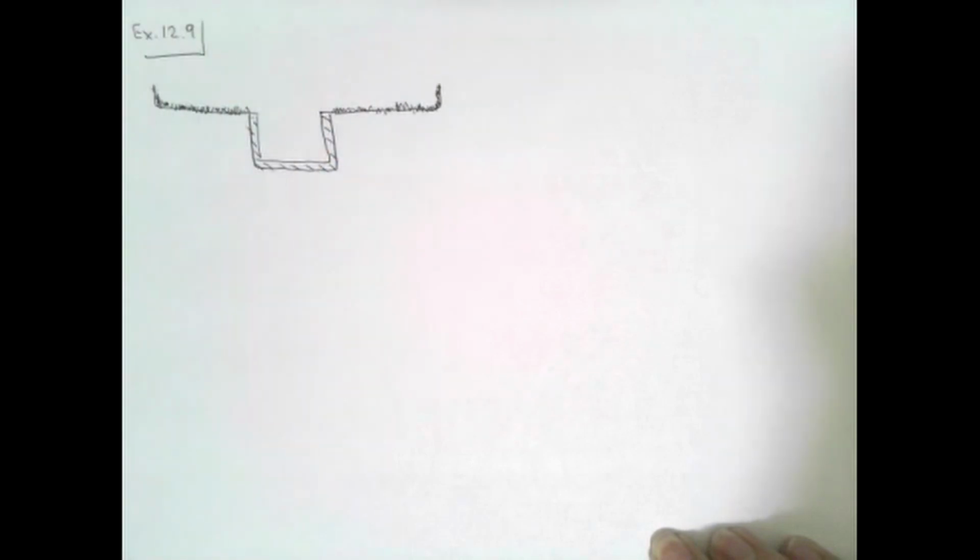And this is going to be a very common type of channel that you'll see in your work as a water resources engineer. We'll see that flow, typically for large storms, does not remain contained within our channel and therefore must flow into the overbanks. So just to talk a little bit about some definitions, the concrete part is called the channel, which is where the flow is intended to travel. And then the outside part is called the overbank.